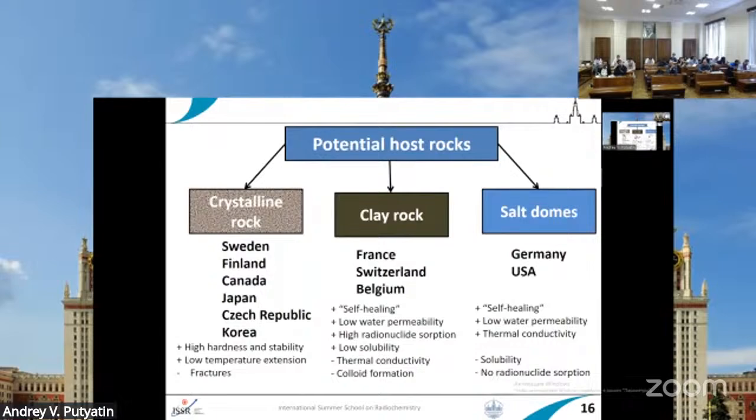For the clay rock, again, they have this self-healing effect because, due to the structure of the clay minerals, they have this interlayer space, and when water interacts with clays, water penetrates in this interlayer space, and the structure expands or swells.